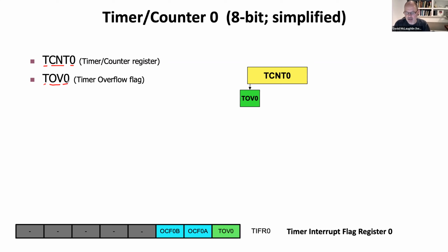Here it is down here. There is an 8-bit register called TIFR0, which stands for Timer Interrupt Flag Register, and we're just interested in bit 1 of it. When we want to find out whether the overflow has occurred, we keep looking at that bit to make sure it has gone high. And that's the one that we set back to 0 every time.